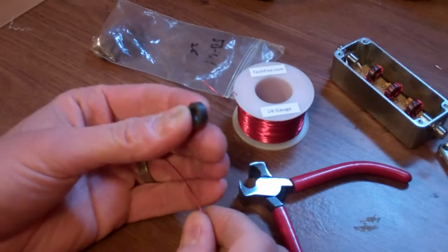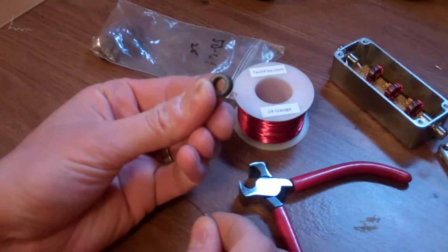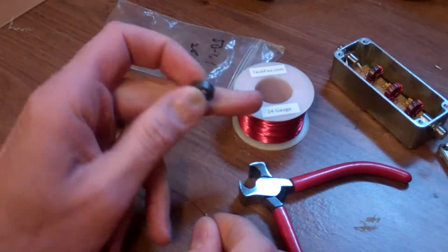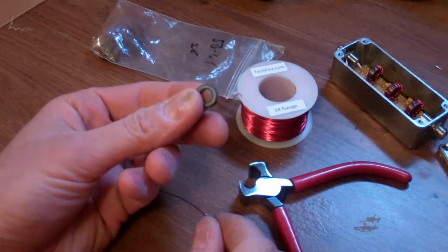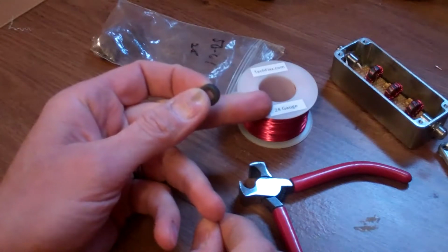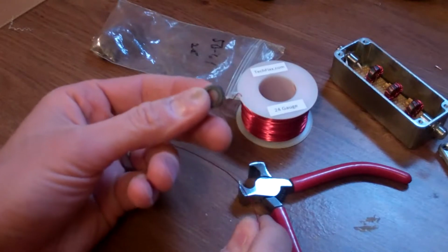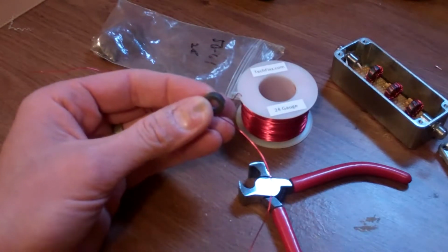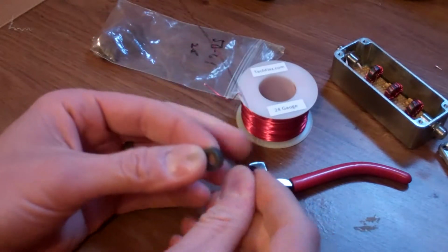So when I start winding a toroid, in this case these are the FT50 type 61 ferrite toroids from, I think, Amazon. I prefer to use a 24 gauge magnet wire. You can use thicker or thinner depending on how many turns. If you have a lot of turns on one of these little toroids, you're going to want a thinner wire, probably 26 gauge, maybe even 30. If you're only putting a couple turns, you can even use 22 gauge. Now these filters I'm building are only for receive purposes. I wouldn't transmit more than a couple watts on them because the wire is fairly thin.